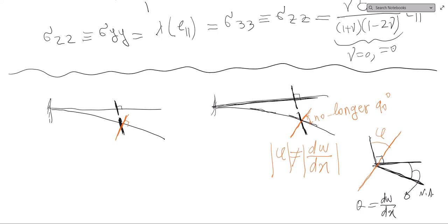This is a very important distinction between these two. Basically, what Timoshenko does compared to Euler-Bernoulli, or engineering beam theory, or technical beam theory, as we discussed in the previous video, is that it gives the beam more degrees of freedom. These extra degrees of freedom come from shear deformation.